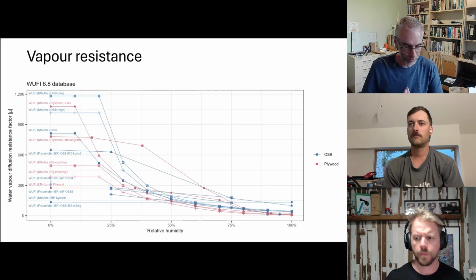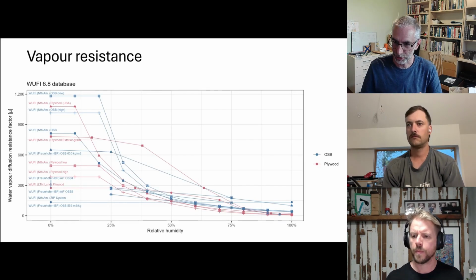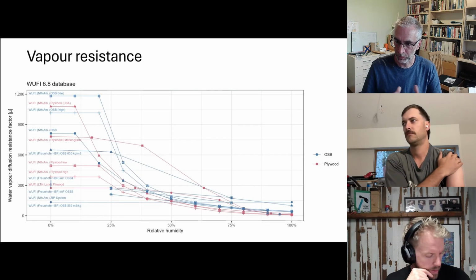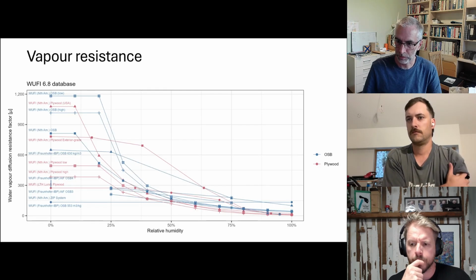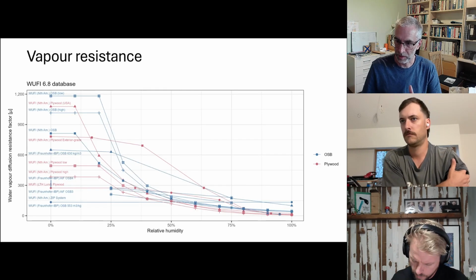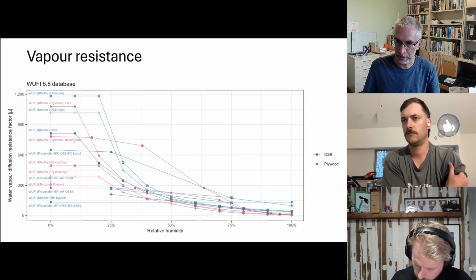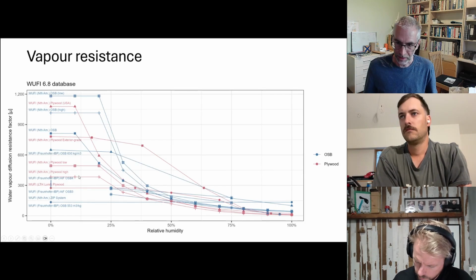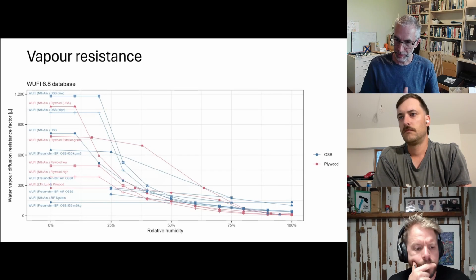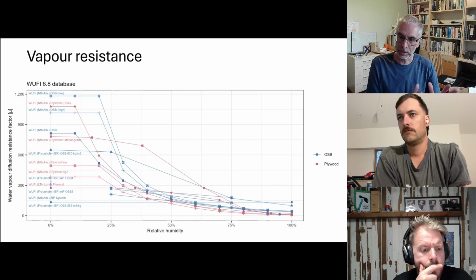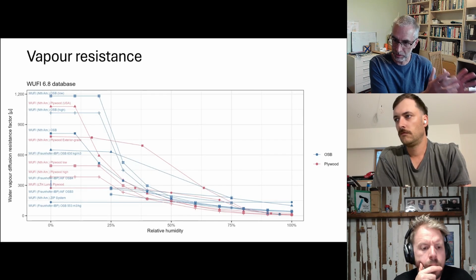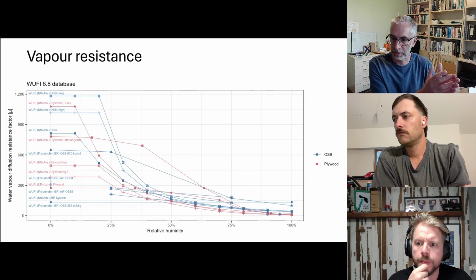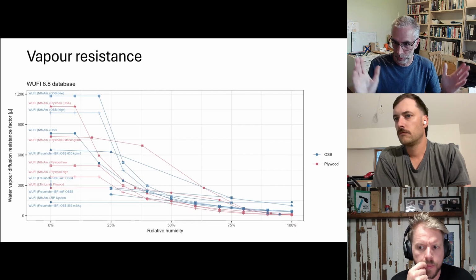And so obviously, anyone on a podcast listening to this is going to really struggle now, because I'm going to present a whole bunch of graphs. But the data that we've got here comes out of WUFI, which many of you have probably heard of, the hygrothermal simulation software that's widely used to try and predict any moisture problems that might occur in an assembly. All of these lines here represent different plies and OSBs within that database. And then that database in turn is sourced from empirical research, so lab experiments, just like the wet cup, dry cup test that I talked about a moment ago, conducted by different laboratories across the world, North America, Norway, Sweden,